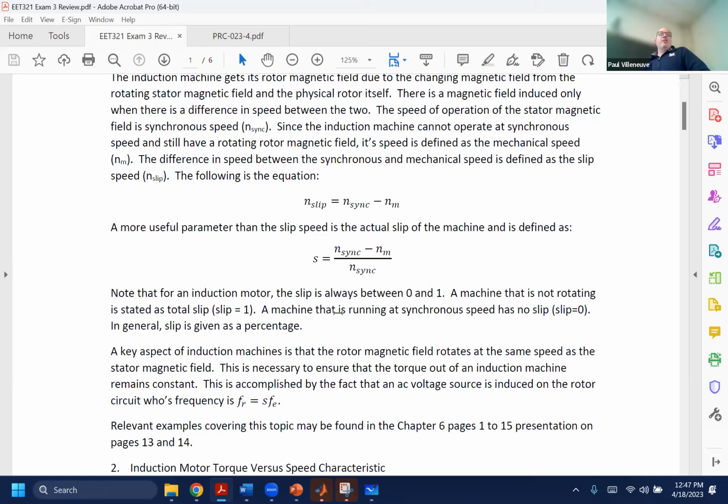Same thing with an air compressor. You're not going to rotate the air compressor to generate electricity, because that's not usually what we do. We want to optimize it for our mechanical output, not for our electrical output. That doesn't mean we can't use braking technology. That's when we would use our electric motor, which is bidirectional and works either way. We can use our electrical device to either export or import, because sometimes we're pushing the wheels and sometimes we're trying to slow them down.